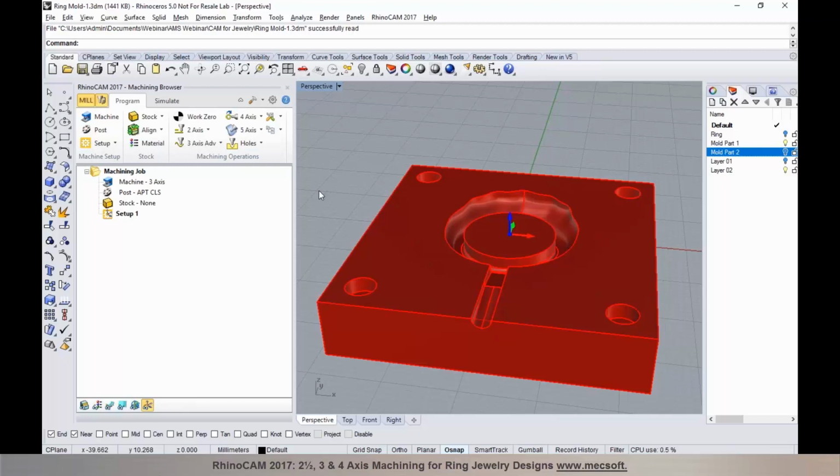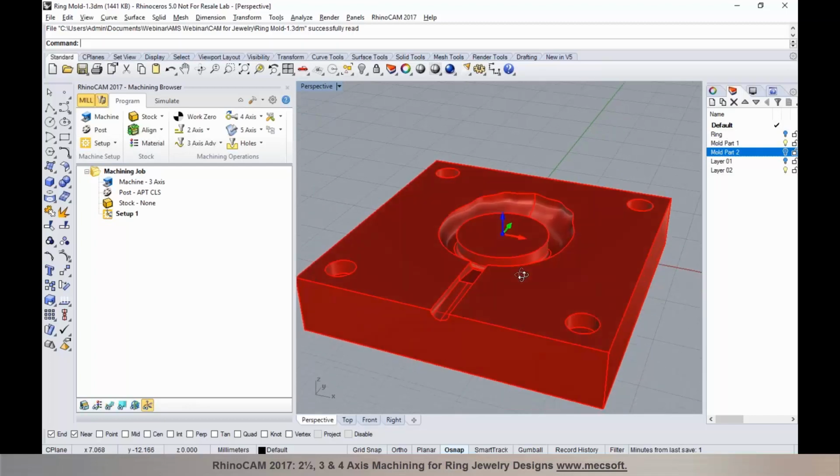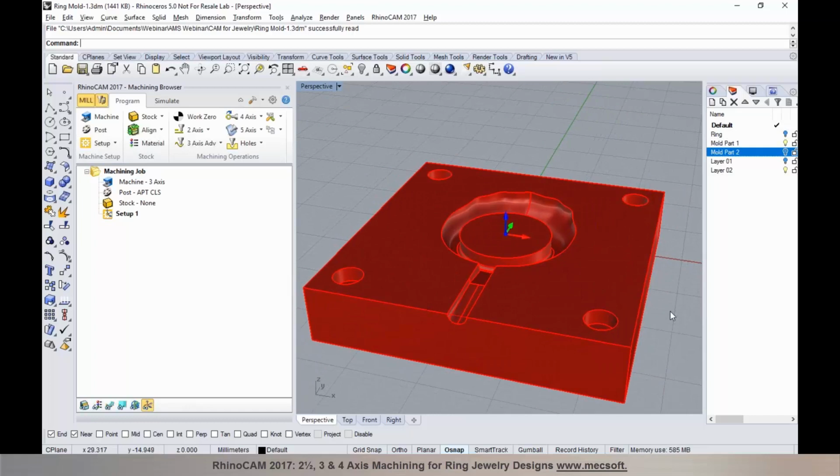In the next step, I just want to interject here for those people who are very familiar with machining wax models. What we're seeing here is molds for creating wax models. You would create a master mold, if you will, and that's used to create a wax model that you would then put up in a tree to create the investment casting. This is one of the processes that a jeweler would typically go through to create the master model, or rather the wax model, of a jewelry item. I just wanted to bring that to your attention. Thanks, Uday. Thank you, Joe.